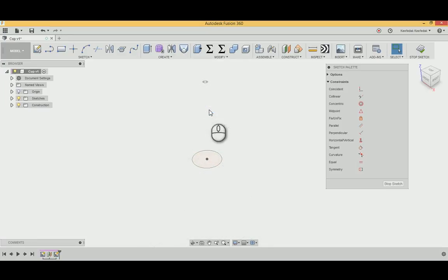You're going to notice there's that bullseye that's floating right up there. That's the origin, the new origin. And so what I'm going to do now, I'm going to go to my cube on the right hand side here. I'm going to hit the word top. Okay, and it just so happened my top laid on its side like that, which I don't like. I don't want to get disoriented. I don't want you to. So do you notice there are these little arrows? Just click the one to rotate it so top reads left to right like that.